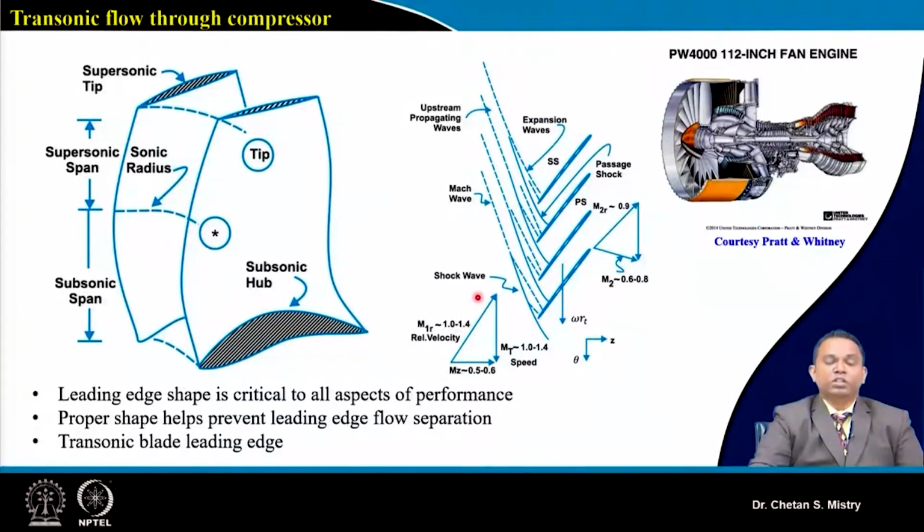Okay, so this is representing my flow, a supersonic flow, entering inside my flow passage. Now here in this case, when it is entering, because of the presence of my leading edge, which is of slightly smaller curvature, that is giving the bow shock to be formed. Because of the surface of my suction surface, here we will be having expansion fans to be formed.